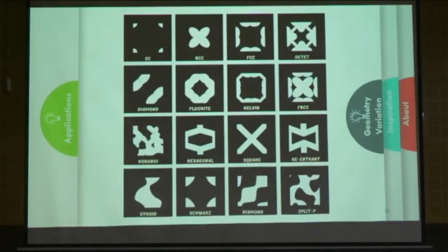And you can see, I told you, right, the strut formation. We printed the BCC, and the problem is with the multiple formation. Here only BCC you can see. The 4 junction points, the 4 points we are seeing, come in contact with each other. Specifically, they told us that for roller-based processes, if anything happens, that will be a problem. So because of the 4 junction points, we are getting a difficulty. In octet, we didn't feel this actually. You can see there, octet. Because octet is a different thing actually. Because of that only, we are getting a problem.